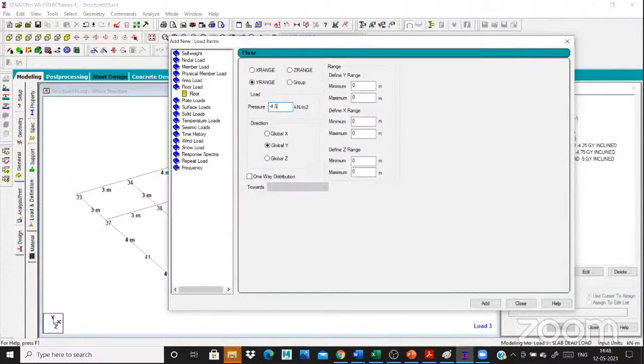Then how to create all the floors? This is the range method. Creating a group is one method. The other method is the range method. Our height is the total floors, right? Height is 0. Already created. Our floor starting height is 3 meter. This floor is 3 meter. Ending with 3, 6, 9, 12.